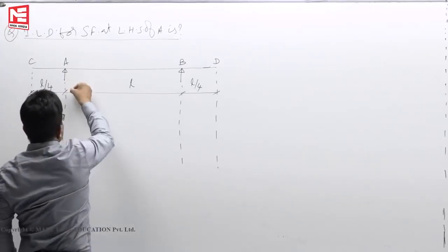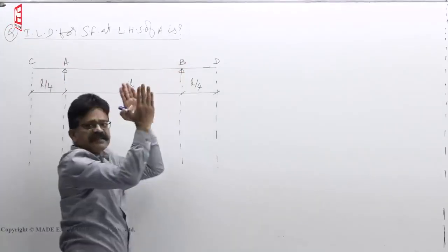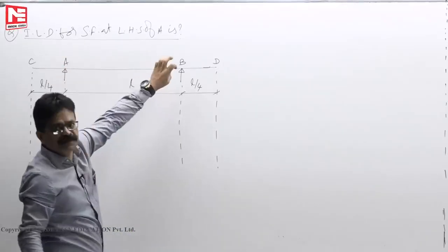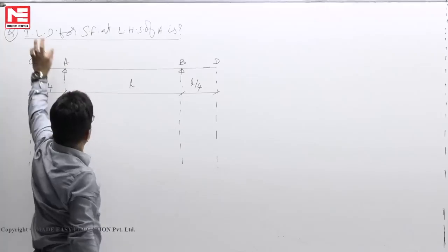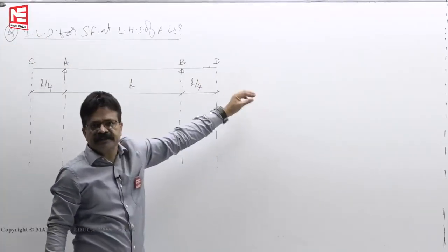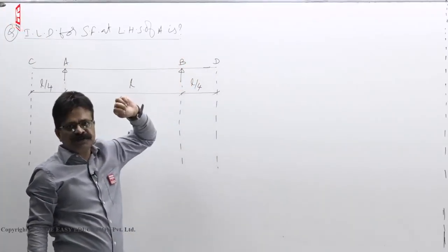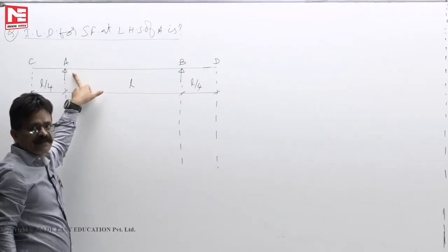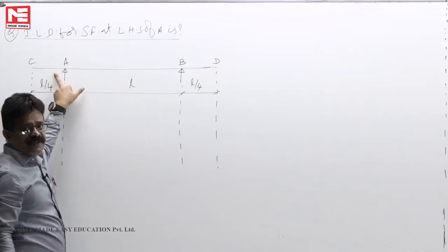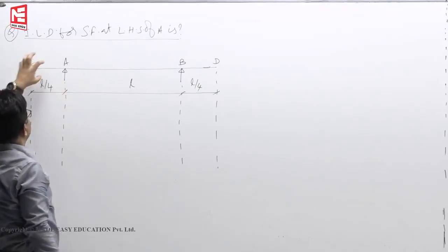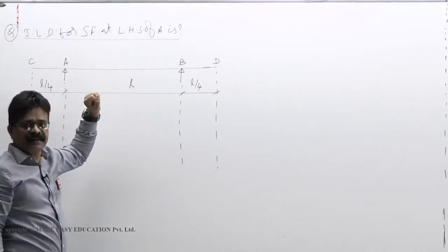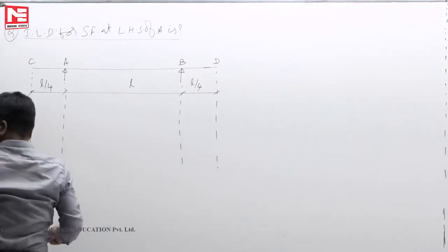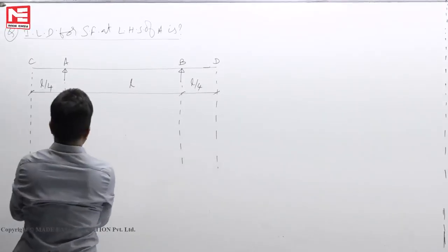Once you cut at RHS of A, the AB span looks like a simply supported span. So you have to rotate, theta A, theta B is equal to 1 by L, and you have drawn one influence line diagram like this. Earlier I explained this for a 2 marks question. RHS of A we have drawn already. At that time LHS of A we didn't draw because the AC portion behaves like a cantilever. We didn't cover it by the time, that was introduction. Now let us see how it behaves at LHS of A.